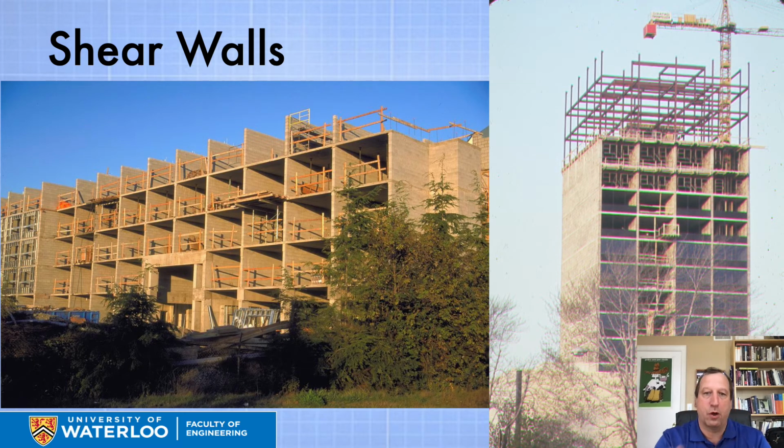If you think of the walls that we can see, call that the X. Well, then in the Y direction, it's running down the corridors. And the only holes are every room's doorway and maybe a spot for some small ductwork. So this is an approach that is used in a fair number of buildings. When you see those big, long, solid walls, you can be pretty sure that the structural engineer was relying on them as a lateral load resisting system.